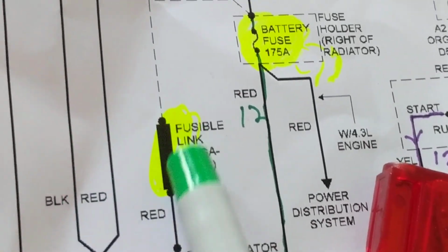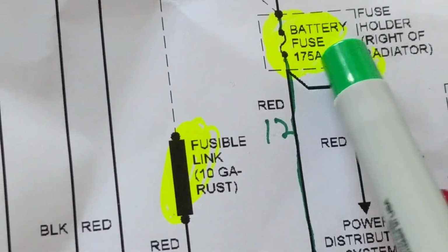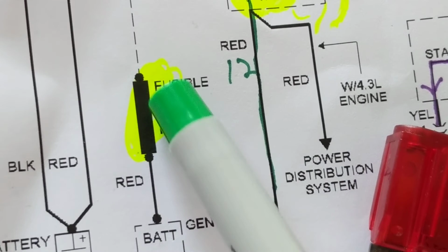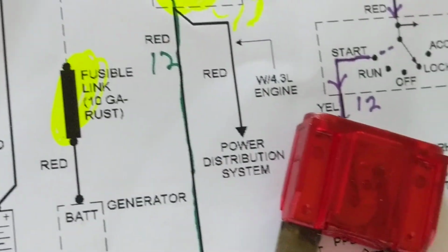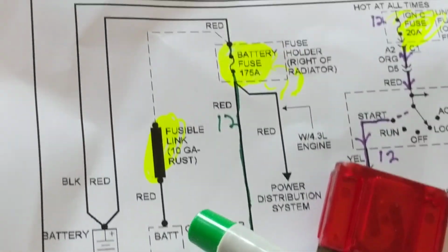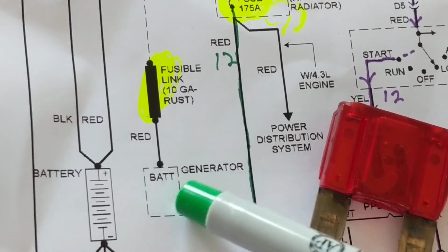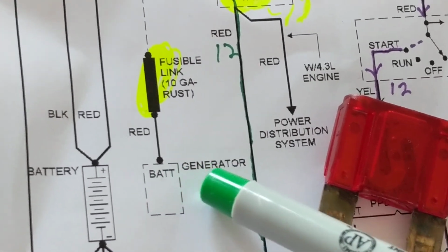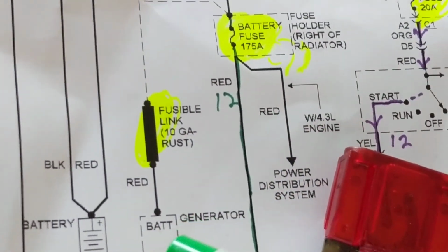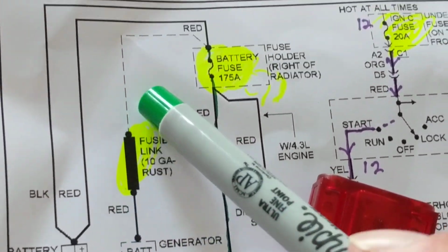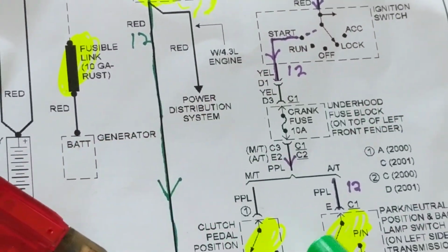As we said before, you will see protective devices. In this one, you see two of them right off the bat: a fuse and a fusible link. Two wires connected together, and they melt at a certain temperature, a certain rating, so they will open and protect the circuit. From the generator, the alternator, an AC generator to DC, it goes over here back to the battery to recharge the battery and also to feed the accessories.